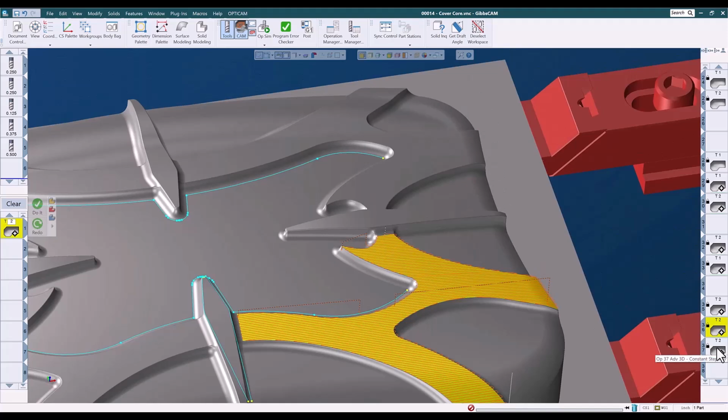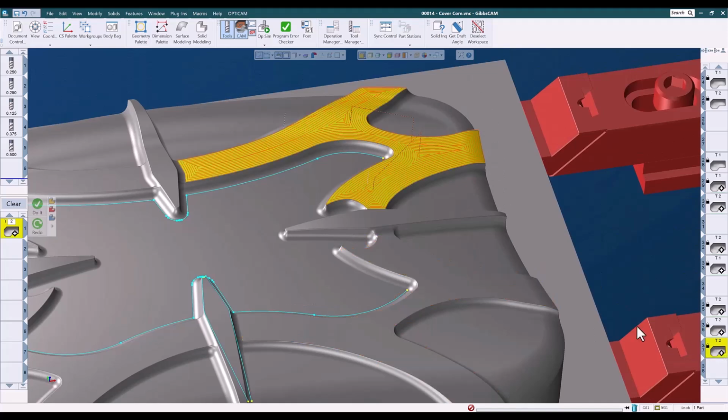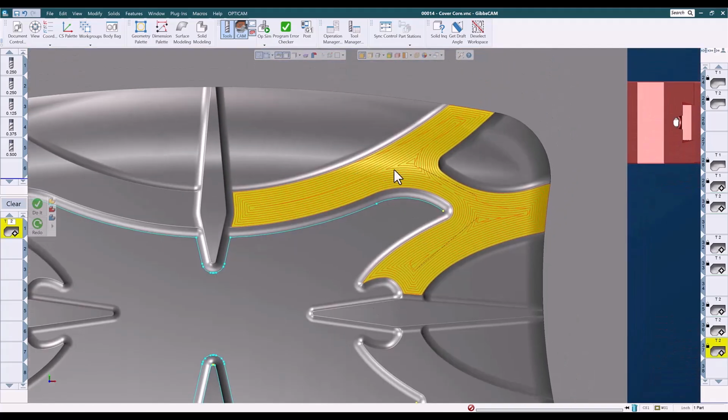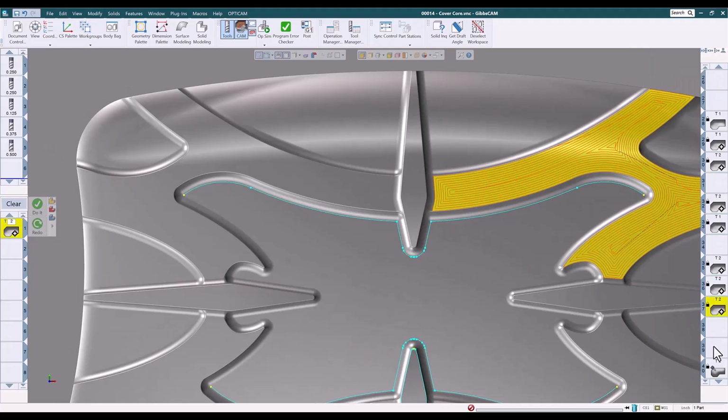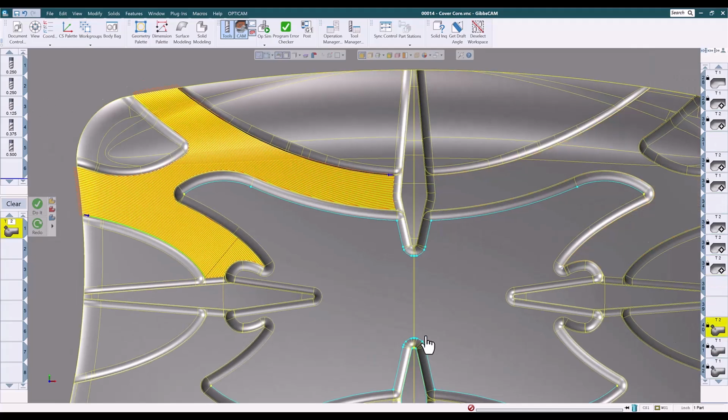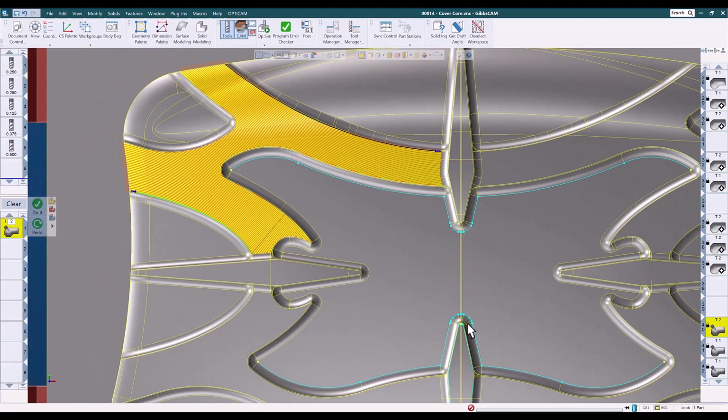Here's an advanced 3D constant step over pattern. This flows perfectly with the area to be cut and only has 2 retracts. This would work very nicely for this shape. And while we're looking at these, let's check out a few of the multi-axis or the 5-axis options for these features. Of course, all of these are set to output 3-axis toolpaths.